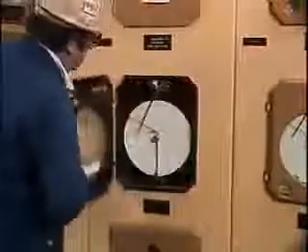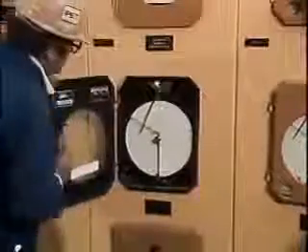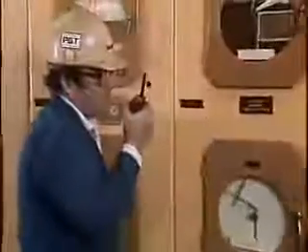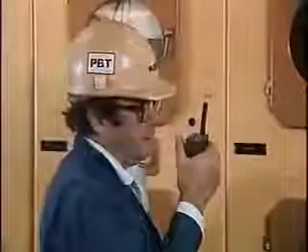The internal parts of the compressor and its driver must warm up gradually to prevent stress and potential damage. For this reason, it's important to keep a close watch on compressors while they're warming up. Once a compressor and its driver have run for a while at a low speed, the compressor can be brought up to operating speed. This involves increasing the speed of the compressor at a certain rate, which is called a ramp rate. The compressor and the driver will continue to warm up as speed is increased. Increasing the speed according to the ramp rate ensures that the compressor's parts warm up evenly.